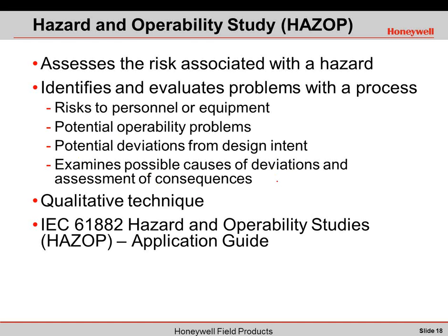So a HAZOP's more of a qualitative versus quantitative technique, and it's based on guide words and is carried out usually by a multidisciplinary team of operators, engineers, and other employees during a series of meetings, and they're referred to as a HAZOP team. So there's also an IEC standard for hazard and operability studies, or HAZOPs, and so they're shown here as my IEC standard for that, 61882.